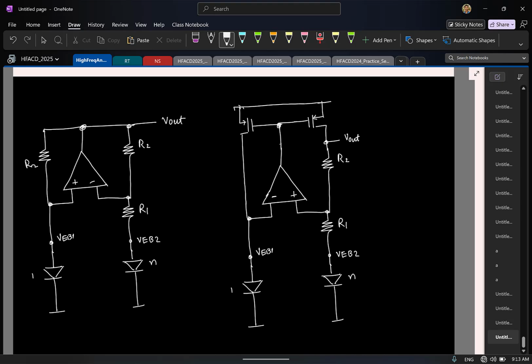So this is one commonly used structure for a bandgap reference. And of course now you see that we have a two-stage op amp, and I'm using it in feedback. So what should I do? I should do some kind of compensation. You can do anything, Miller or something, or sometimes you can just put a large cap at one of the nodes and push one of the poles to a very low frequency and compensate. That is up to you. I will not show compensation.